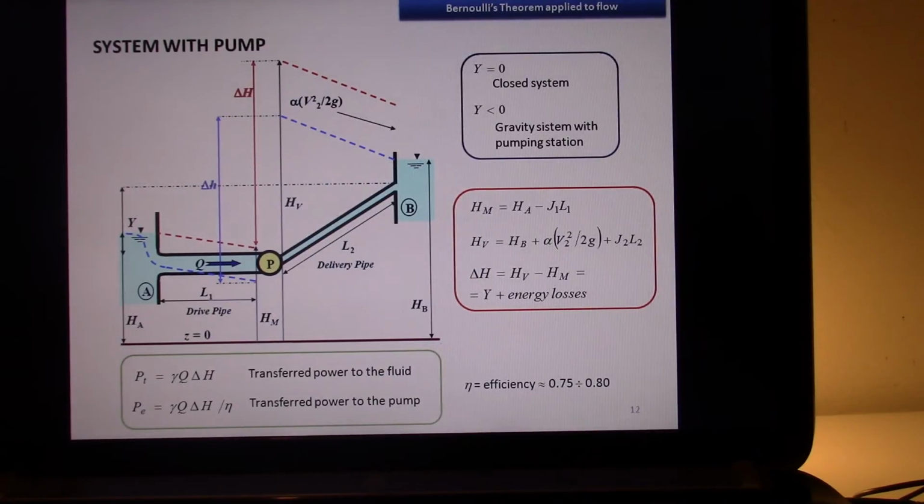So you have a pressure that is almost equal to the vapor pressure of the water. In this case, if there are bubbles, they tend to destroy your machine. Not exactly to say that they destroy the machine, but they lower the level of efficiency of your machine, so it's not able to work anymore.